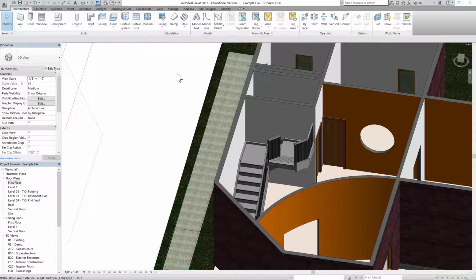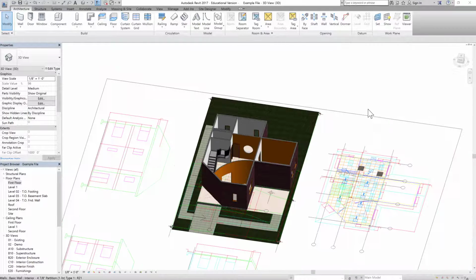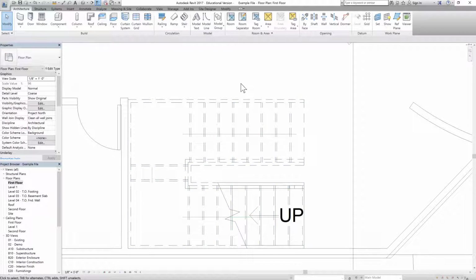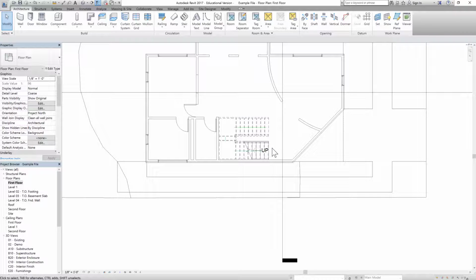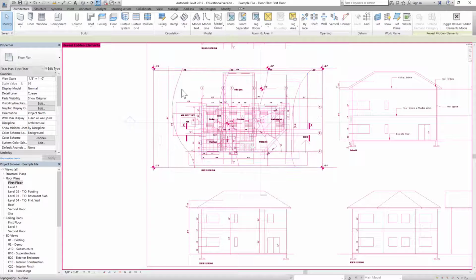Hi everyone, welcome back. In this video, after modeling the staircase, we'll insert a floor and then we'll model the floor opening. So, just to make sure that we have stairs going from this first floor level to the second floor. And because our 2D CAD drawing is hidden, let's go ahead and unhide it.